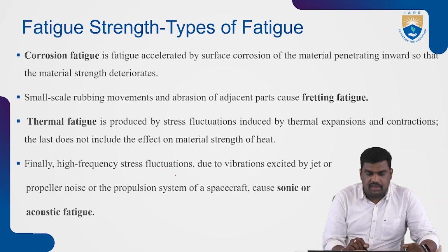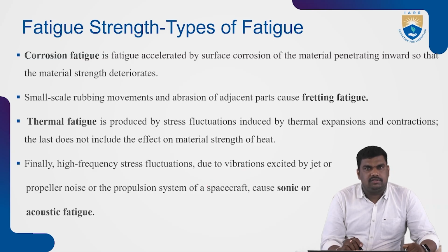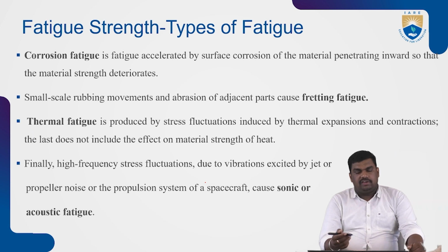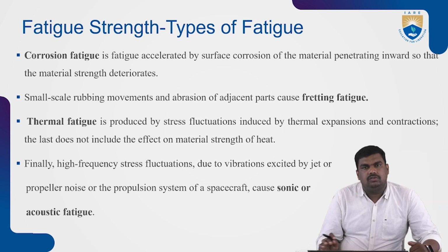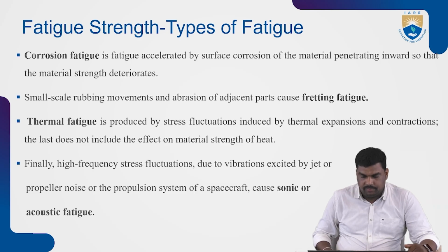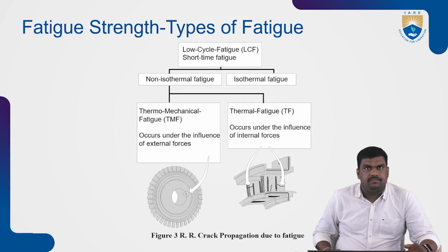Finally, high frequency stress fluctuations due to vibrations excited by jet or propeller noise, or the propulsion, are called sonic or acoustic fatigue. Due to the vibration when the propeller or jet engine is running, acoustic vibration is created, causing sonic or acoustic fatigue.